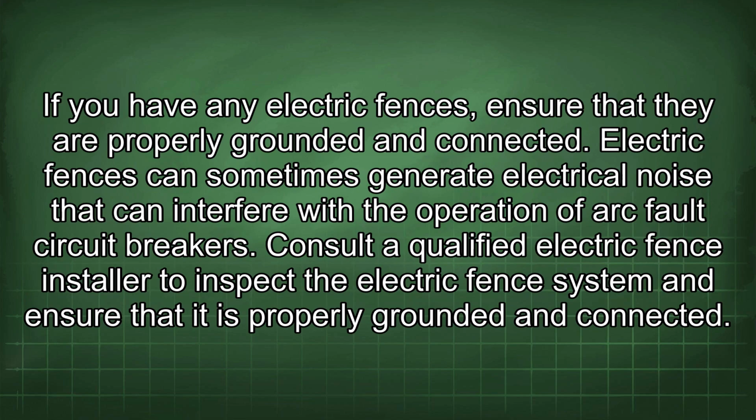If you have any electric fences, ensure that they are properly grounded and connected. Electric fences can sometimes generate electrical noise that can interfere with the operation of arc fault circuit breakers. Consult a qualified electric fence installer to inspect the electric fence system and ensure that it is properly grounded and connected.